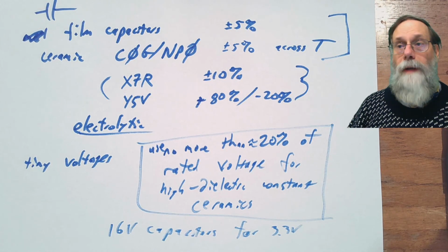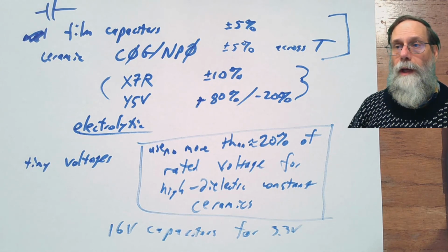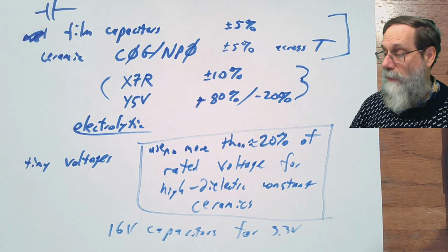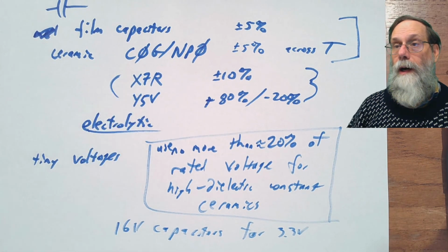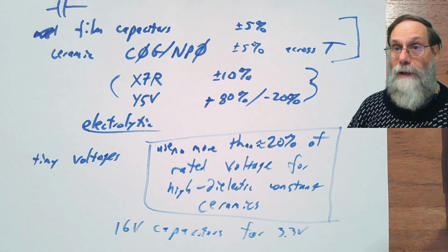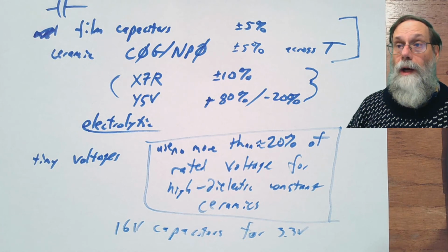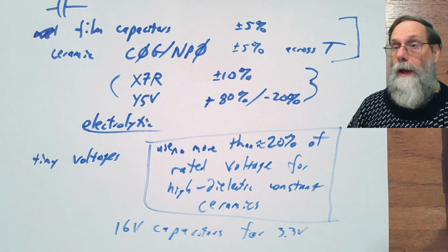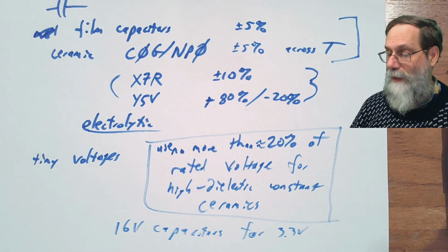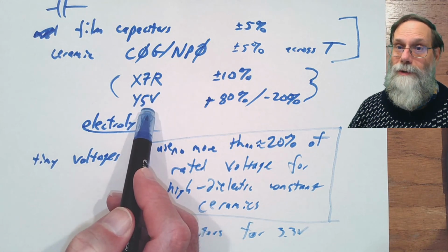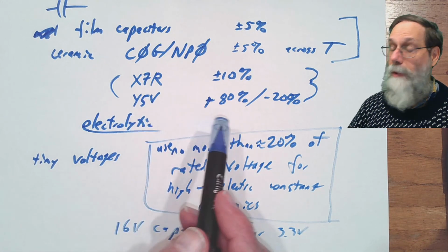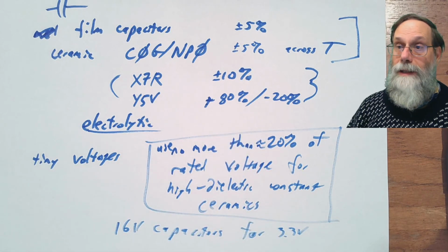Okay, so capacitors, a little bit different situation than for resistors. Again, the cheapest ones here may not be that precise. And the ones that we have in class, I don't have any idea what dielectric they use. They're not labeled, and they're probably the cheapest, which is usually the Y5V or something like that. And so they may be quite a ways off from the ideal capacitance. So if you're trying to do something which is a carefully tuned filter, you probably don't want to use those really cheap capacitors we had in class.